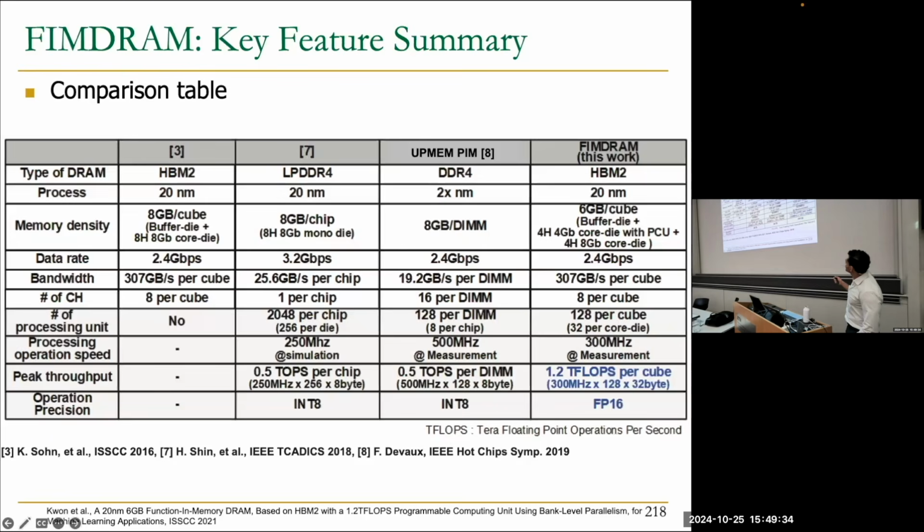It's important to say that a cube is way more expensive than a DIMM, because manufacturing 3D stack is much harder than manufacturing 2D DRAM. Since they are 3D stacked, they have way more bandwidth per cube compared to the bandwidth inside the DIMM. Similar to what we saw before in UPMEM, the clock frequency of the processor is not so high, again, because manufacturing logic using DRAM manufacturing processes is complicated, even for a memory manufacturer like Samsung.